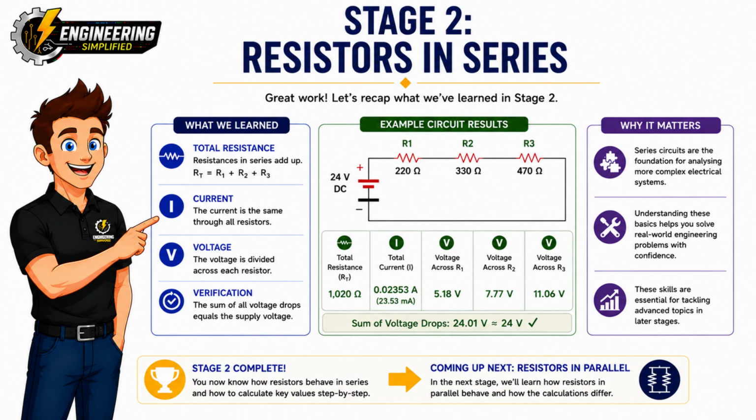Let's quickly recap the key ideas. In a series circuit, the total resistance is found by simply adding all of the resistor values together. Because there is only one path for the current to flow, the same current passes through every resistor in the circuit. The supply voltage is then shared between the resistors, with each resistor producing its own voltage drop. And finally, if you add together all of those individual voltage drops, they should equal the original supply voltage. That's one of the best ways to check that your calculations are correct.